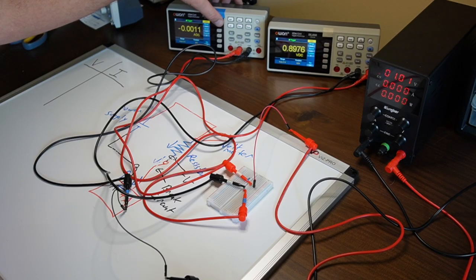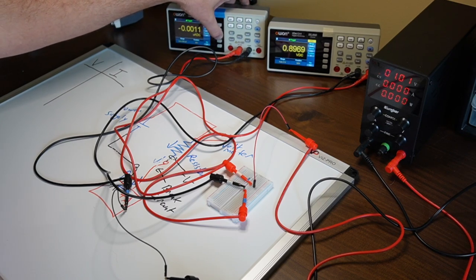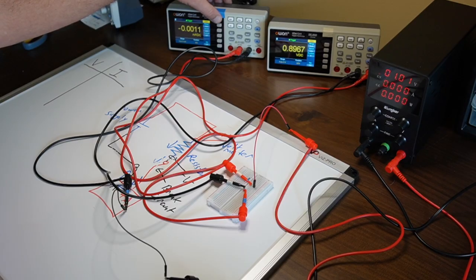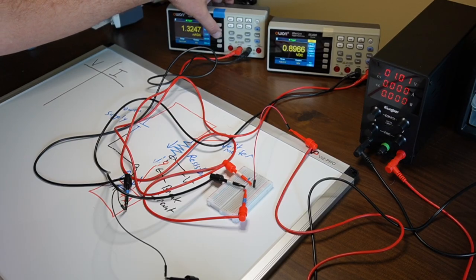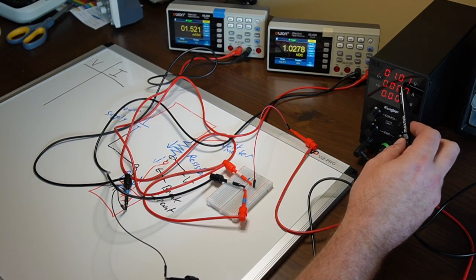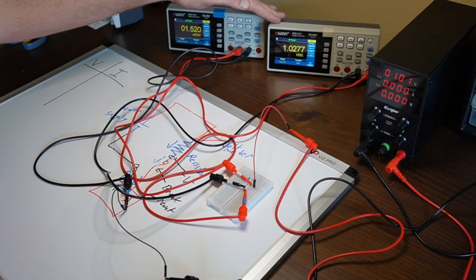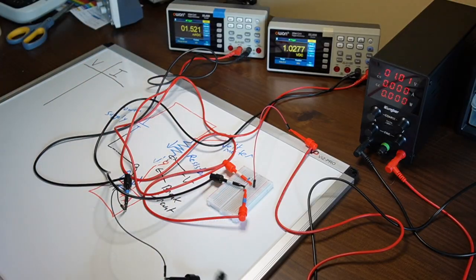So I got about 1 volt applied, and let's make sure that we are in the range that we want to be in. And so let's see, that's auto range there, I think. Why is it not allowing me to do that? Okay, function, milliamps, okay, that's what I want. And then we're going to do 50 milliamps. Okay, so that will be a good range for us. Okay, so now, even though this says 1.01 volts on the power supply, we're not going to trust that value. We're going to trust our multimeter values that are reading right at the resistor.